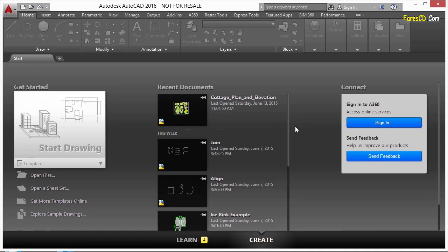Many times in AutoCAD, you need to be very specific about what objects you're selecting. Most of the time, you're just going to directly pick what you want. But let's say you wanted to pick a whole bunch of things all at one time with very little effort throughout a big area of your drawing. Well, you can use the Quick Select feature.